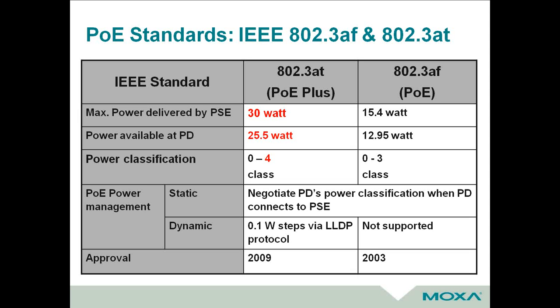And unfortunately, there are a bunch of vendors out there that are pushing the limits of power, and maybe they design closer to 26, 27 watts of power at the end, and there just isn't enough power to power their device. And one of the things they've done to get around it is they have brand labeled their own power over Ethernet injectors and sell them as a kit. Now, we figured this out over the years of doing this protocol and have some unique solutions we'll talk about further on in the presentation to address those slightly out of spec products that are out there.